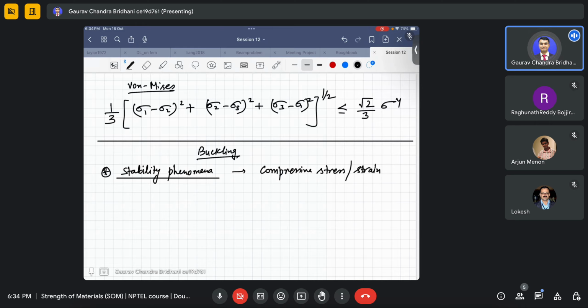There are different types of buckling. Buckling happening in a column is different from buckling happening in a beam. The top flange of the beam is also subjected to buckling, which the professor has touched upon in the lecture. That is called lateral torsional buckling, or LTB, which happens in the beam. Then there is shear buckling, which happens in the web of the beam also. In steel girders, the girders mostly take the shear, as we have seen in beams when we go further for some higher courses, when we make the beams of I section.